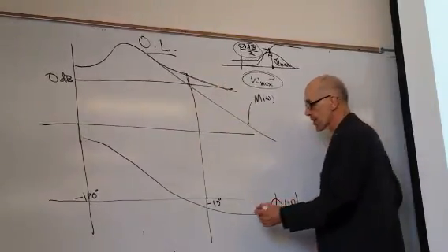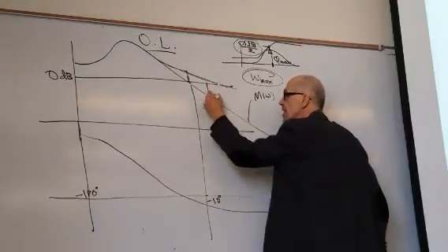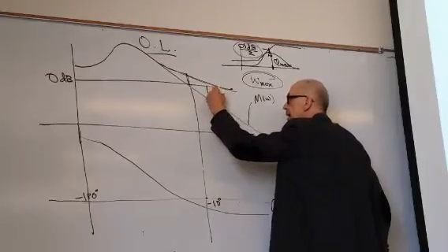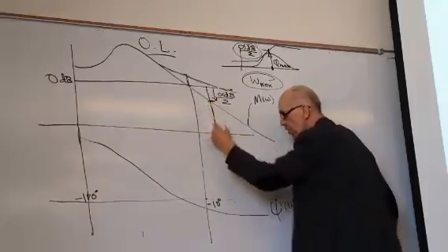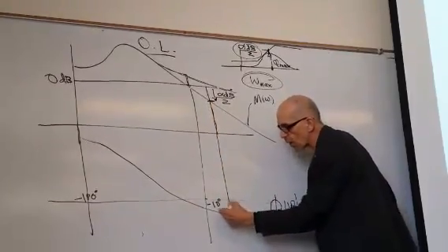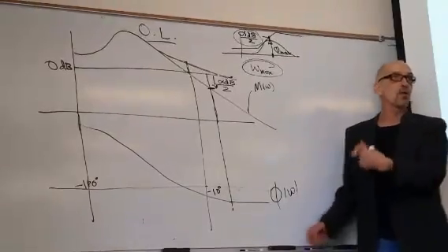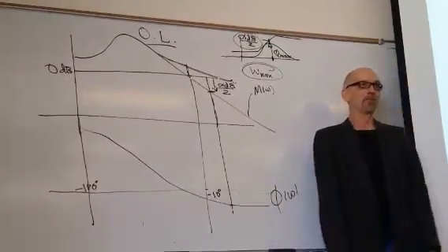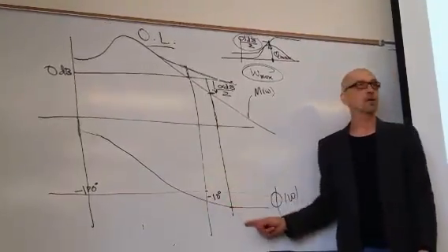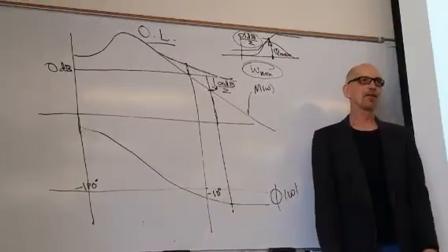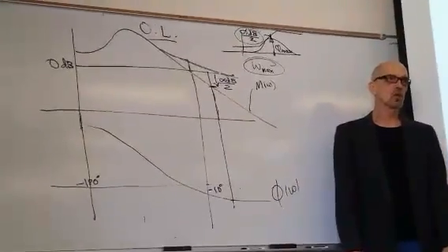So you go to where you're down alpha dB over 2, say here, and then you go to the phase here, and if that phase isn't a whole lot different than minus 170 or 190, suppose it's 195, boom, you're done. If it's 200, 210, because it's really dropping fast, time to iterate. So like 5 or 10 degrees should be okay? 5 to 10 degrees, usually.